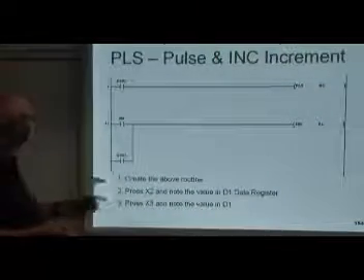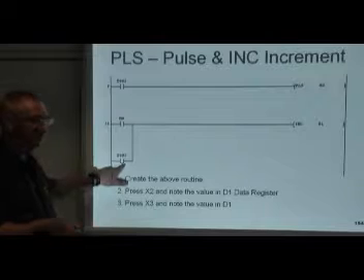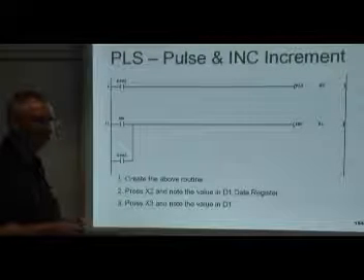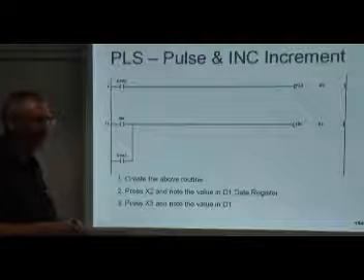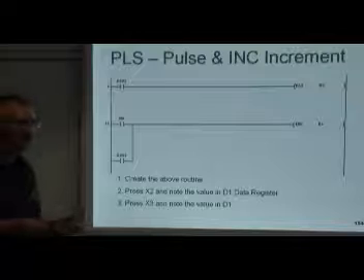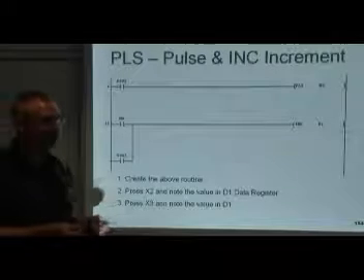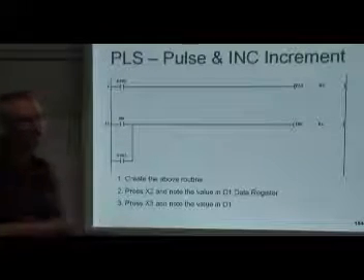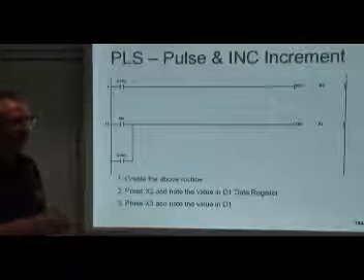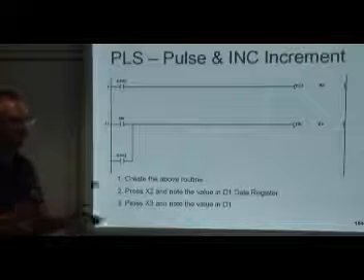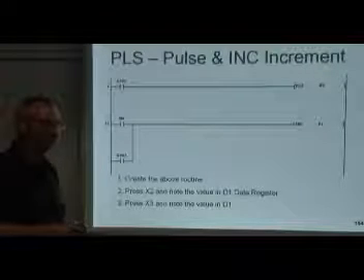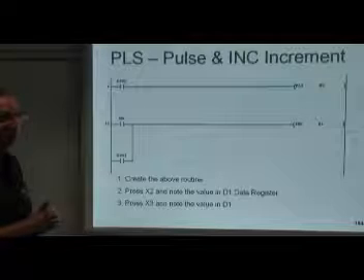Right, if you press this button here on your test rig and then let go, what's the value now? 139. 139. So with 2 millisecond scan time, we've got 139. That meant that that button was pressed for 2 times 139, so you're looking at 278 milliseconds. That's how long it was actually pressed for. It's counted that number of times inside of there.